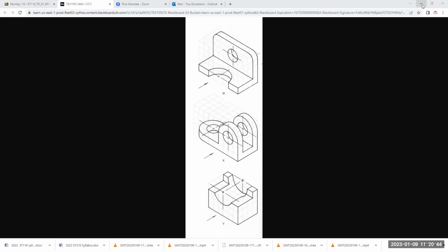Okay, so that's probably the most out of beginning AutoCAD. If I can get that through to a student, then I'm done good in 10 weeks, to where they can really understand it and control it. So the control part is really with text and dimensions. We're going to draw everything 1-to-1 here. If it's 800 meters, I'm going to draw it 800 meters. But getting that down onto a piece of paper with the right size dimensioning, that's kind of the tricky part.